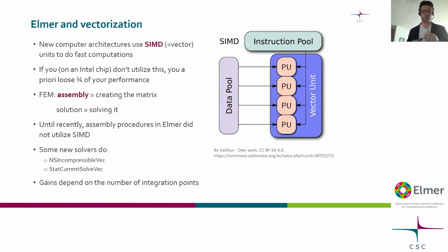It should be included in your compiler suite, like for instance the GNU suite, but also commercial products like Intel have OpenMP enabled. To enable it in the configuration for the compilation of Elmer, you have to switch a flag with OpenMP in the CMake command to true. Then it will start looking for OpenMP and include it.